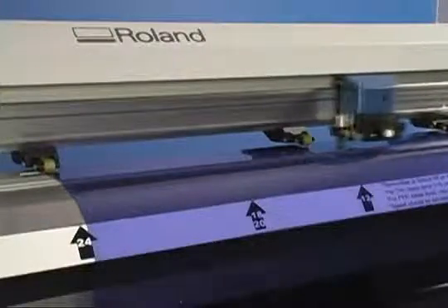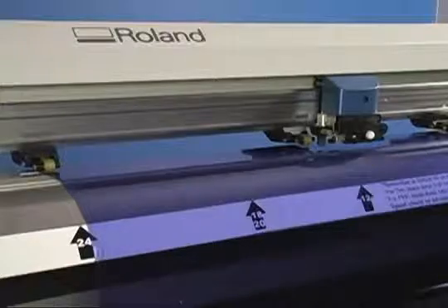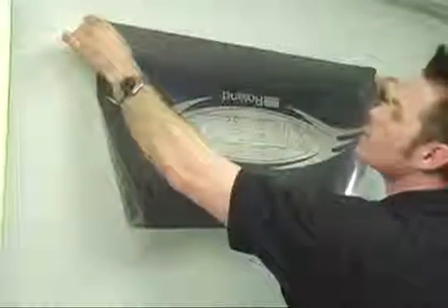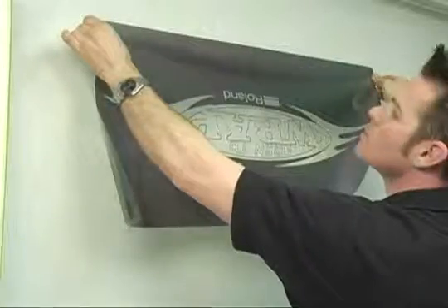Once all of your cuts have been made, it is time to prep the graphic for installation. It is important to keep your work areas and your film clean and free of dust or debris. A good tint install must not have any dirt between the film and the glass. Start by applying your transfer sheet to the glass with the liner facing out. Remove the liner while spraying the exposed adhesive. It is important to keep the adhesive wet so that it will not pick up any dirt or dust from the air. Next, take your template layer and apply directly over the transfer sheet.